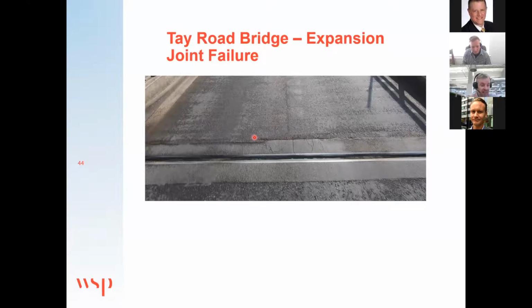We then got the RTK correcting, 15 millimeters, very good corrections. That all helps, and you can correct the data. I'm not showing you in detail; the teams will show you the Examiner stuff. What's really funny is, when we did the surveys, we used the joints to line up the data sometimes because it was just slightly off, and that just happens. But because of the joints and this survey data, we could correct things like that.